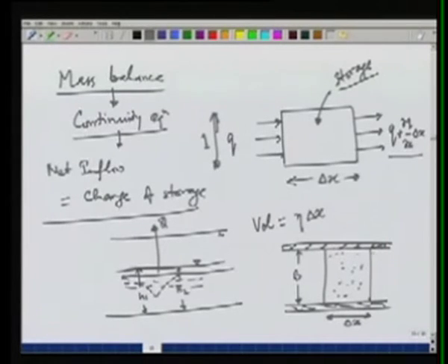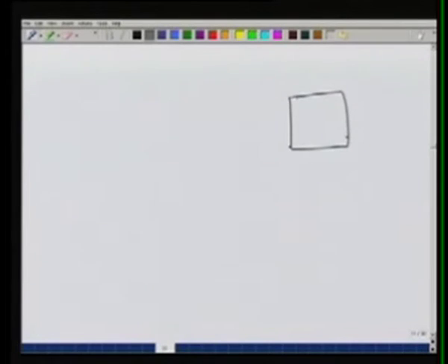But here in confined aquifers, the area and therefore the volume is not changing with time. Therefore, the mass can change with a change in the density. And here the compressibility of water as well as the soil will be important. As we know, the soil is compressible.